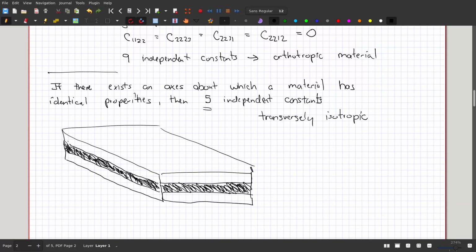And you want to do a simulation on the whole aircraft in flight, right? You know, like the Boeing 787 is made of composite, like it's a composite wing skin, right? So imagine this is like some composite layup of different materials, and you want to do a simulation of the wings in flight, right? Well, the fastest computer in the world is not going to allow you to have that kind of resolution where you can model each individual layer. So what you do is you homogenize it, right? You say, okay, this is one material, right?